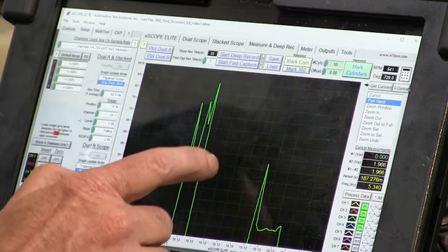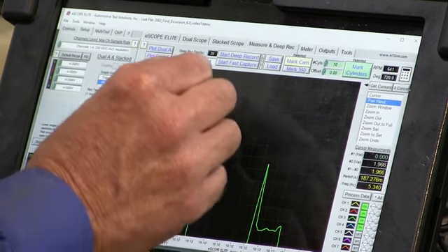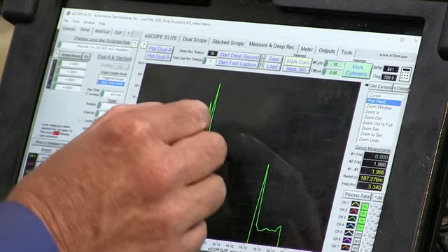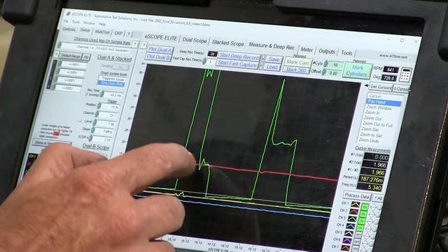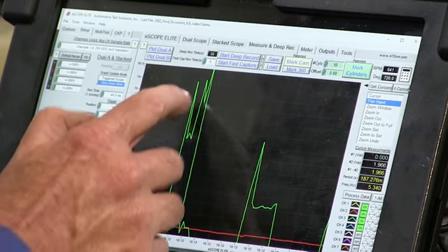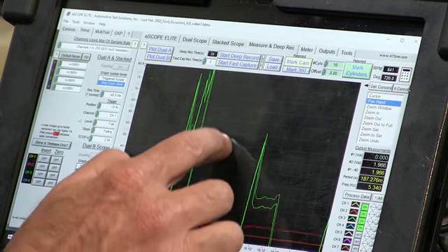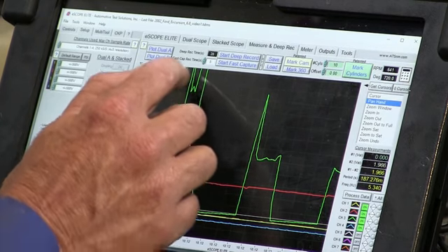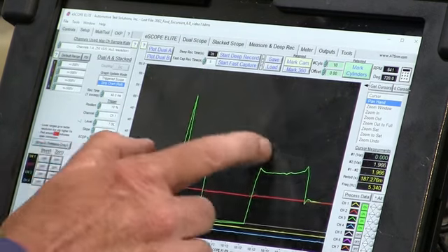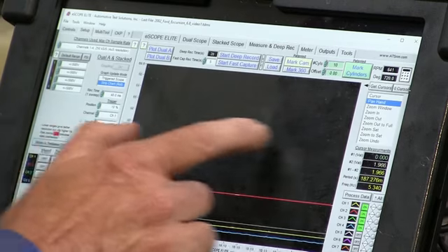Because if it wasn't a carbon arc and I had a lot of turbulence, it wouldn't be able to dissipate all the energy in the coil. And then that spike, that negative going tail would have to be bigger. With that much turbulence and that short a period of burn, the tail would have to be bigger if that really is going across the spark plug. So I don't think that's going across the spark plug right now, guys.